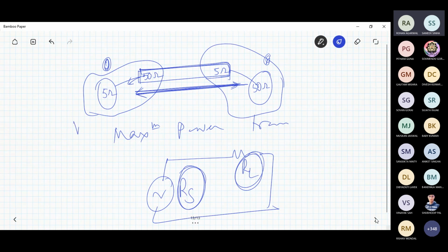So this is your source resistance RS together, 5 plus 50. This is the load resistance, and I have made RS equal to RL purposefully to follow the maximum power transfer theorem. Now the power will be transferred maximally, and definitely you have to pay a cost for this circuit. This is called a matching network, or impedance matching network, or impedance matcher, whatever you say. Could I answer?